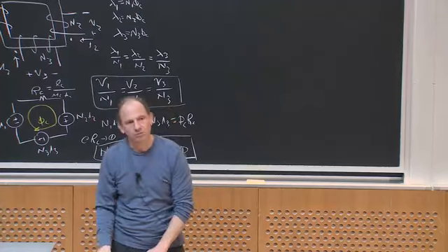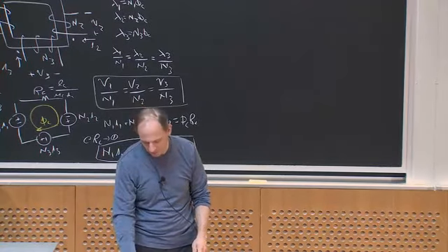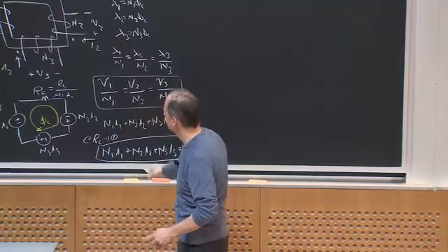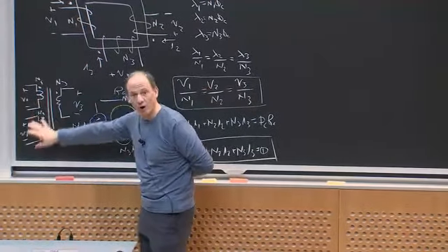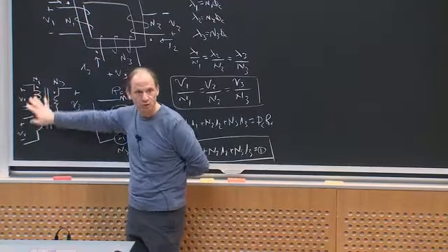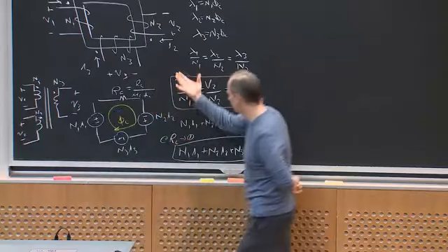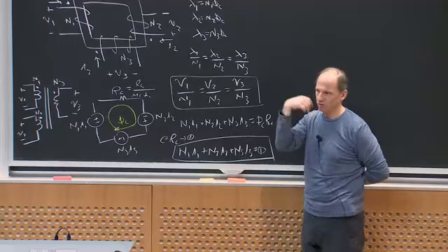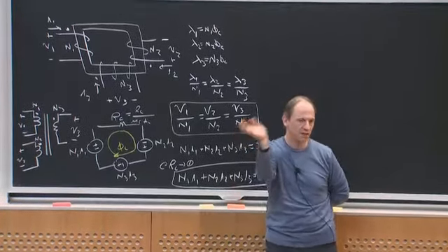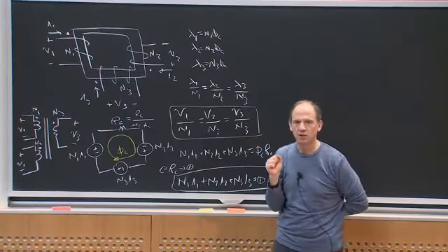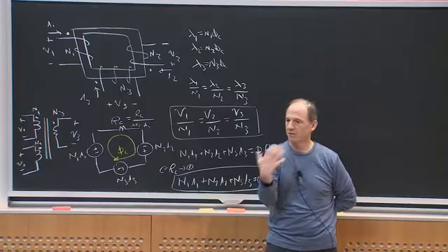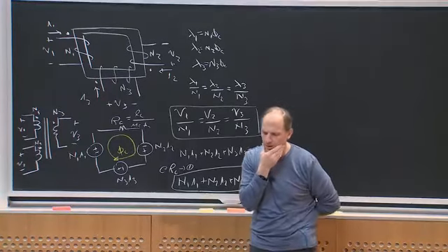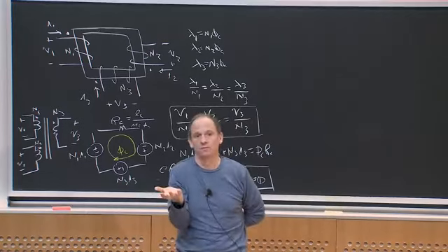So let's think about other possibilities, however. This is perhaps the most common way to build a 3-winding or 5-winding or whatever transformer, where we're going to get a bunch of voltages at the terminals that are ideally ratiometrically related, because that's the most common thing we want. We'll see next week cases where we might want to do that for converter design purposes. But it's not the only thing you could do.